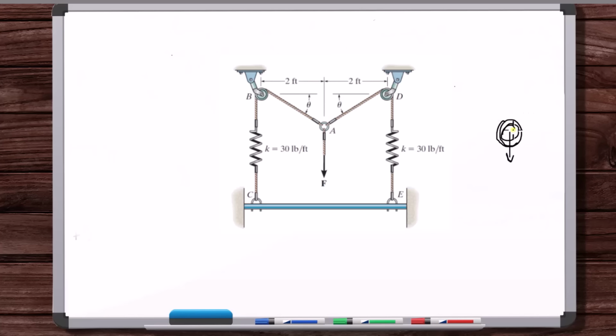The ring would come up here. The forces from the string would be here. If you applied a little bit more load, then the forces would come to here. And the idea of a rigid body is that the lines of action of the applied forces don't change once you apply them. So the ring is a rigid body, but this system and this free body diagram is not a rigid body. But you can still take a snapshot even in a non-rigid system and do a free body diagram. You just specify whether you are holding this ring still when you took the picture, or whether it is accelerating. You have to specify.